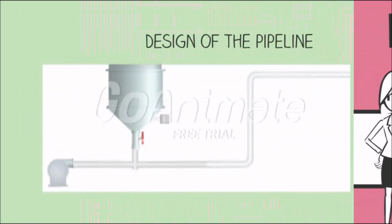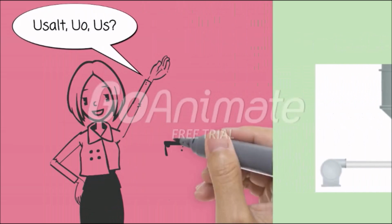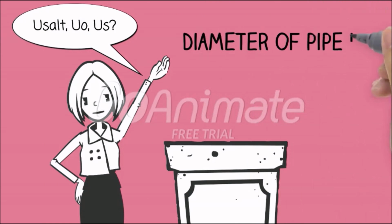This is the design of the pipeline. A blower is installed to allow the tea to flow. Detailed calculations are done in order to calculate the pressure drop from the extracted information. From the previous calculation, the opening diameter of the hopper is 0.45 meters. Based on the American standard, the diameter of the pipeline chosen is 0.45 as well.